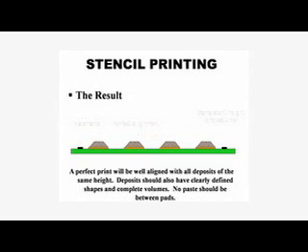Finally, the results. A perfect print should be well aligned with all of the deposits being of the same height. Deposits should also have clearly defined shapes and complete volumes. No paste should be left between surface mount pads.